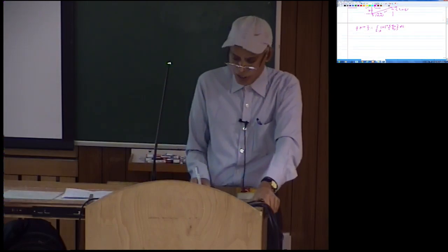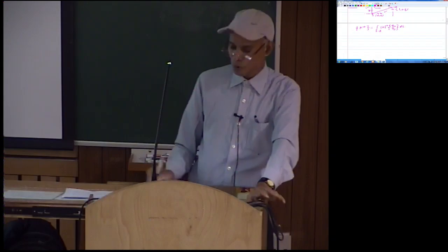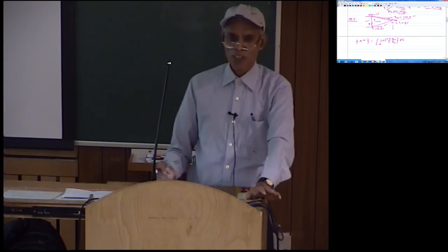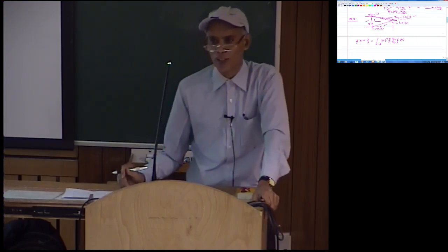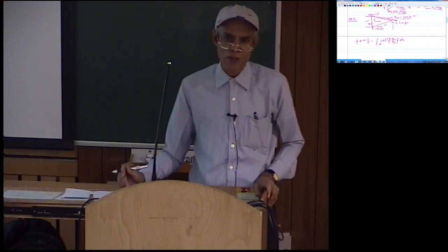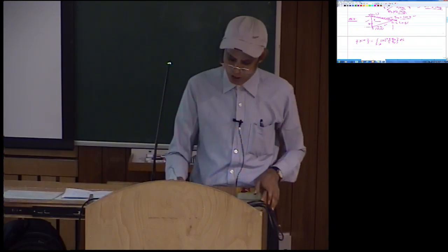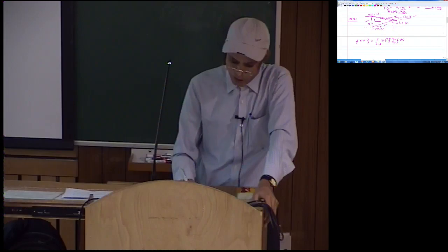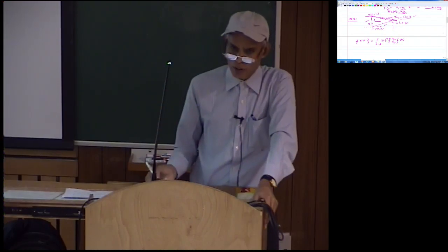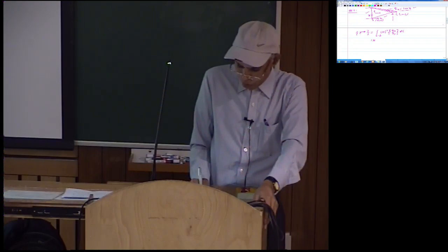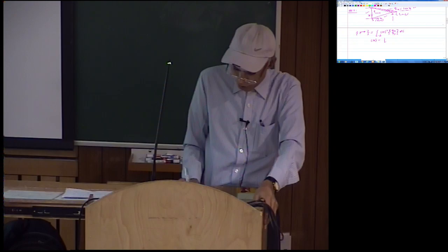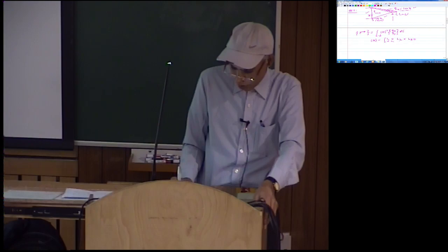So H transpose here, now it's a triangle. Of course you had two options, because we had also discussed that triangular elements can be derived from the four noded isoparametric element also. So you can derive the load vector from there, but in this case it was your choice. It is easier to use the area coordinates in this case. So then you have three nodes directly, and therefore your H is simply going to be L1 0, L2 0, L3 0, and then 0 L1, 0 L2, 0 L3. So this is your H.